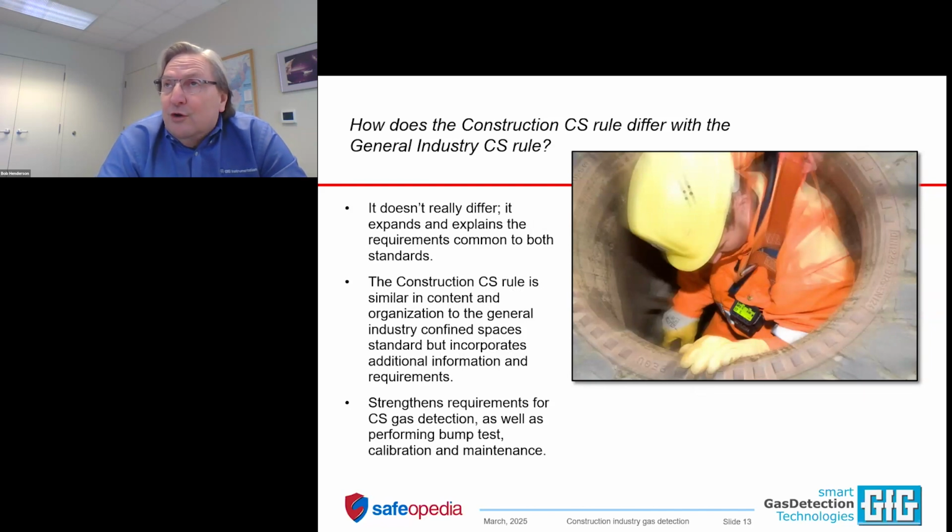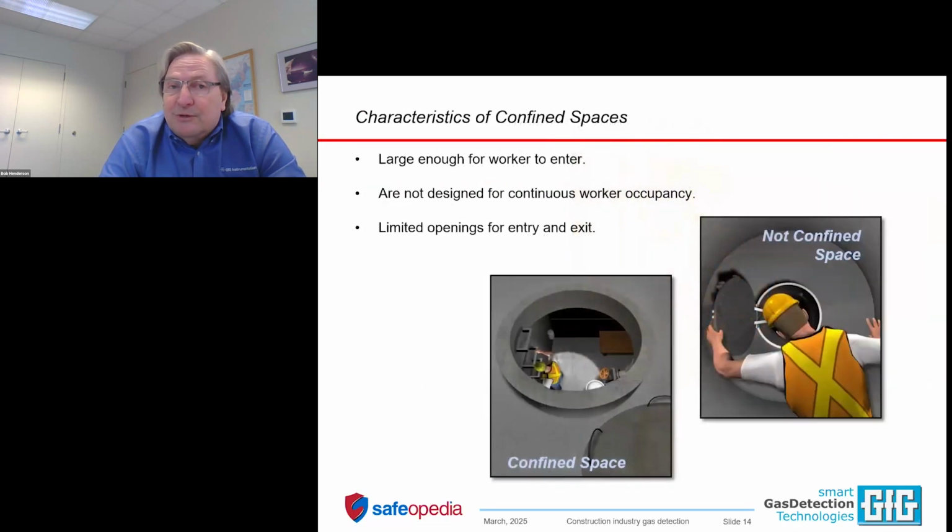If you rig your whole program along the lines of the construction confined spaces standard, it's going to work for the general industry standard as well. There are no fundamental disagreements between the two standards. The definition of a confined space is exactly the same. A confined space needs to be large enough for the worker to enter. It's not designed for continuous worker occupancy. It has limited openings for entry and exit.